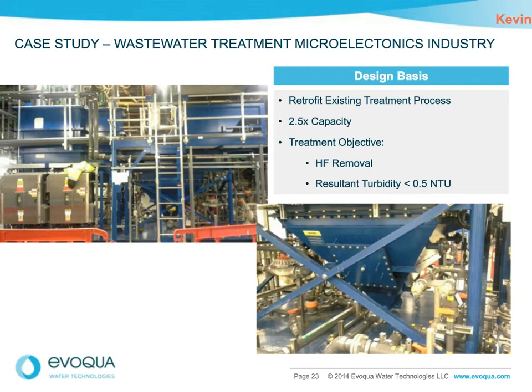The system was originally designed to treat hydrofluoric acid using lime. Since space was at a premium, the expansion had to take place in the original space that the wastewater treatment system already occupied. The system was retrofitted with duplex inline shear mixers and duplex magnetic recovery drums. The existing lamella clarifier was modified, and they used the existing reaction tank system.